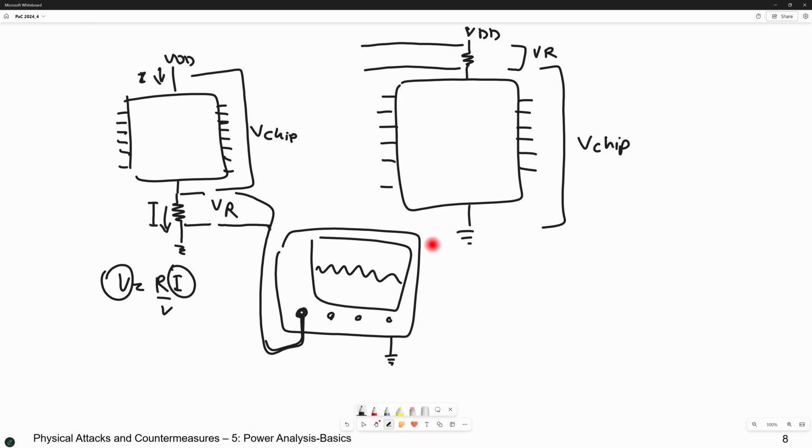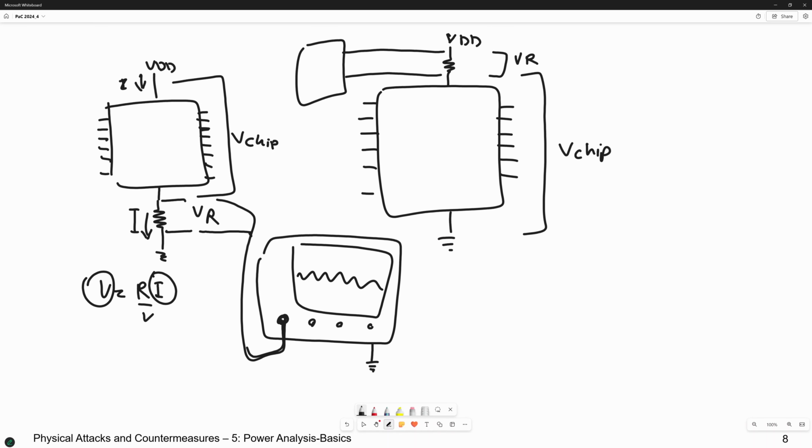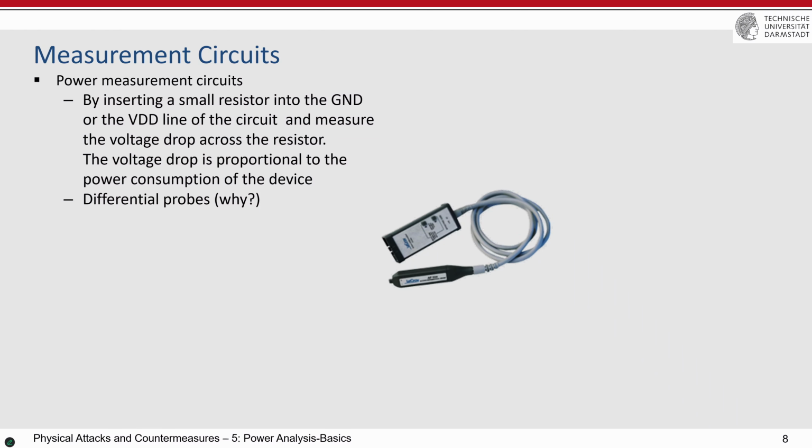When you want to measure something, it's recommended to connect the ground of all devices together. Then you cannot connect these two to the oscilloscope if the earth or ground of them are the same. Then you need another device in between, which is called the differential probe. Means that you connect this then later easily to here, and this differential probe measures the difference between the voltage of these 2 points.